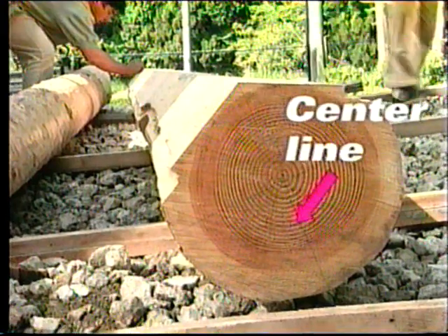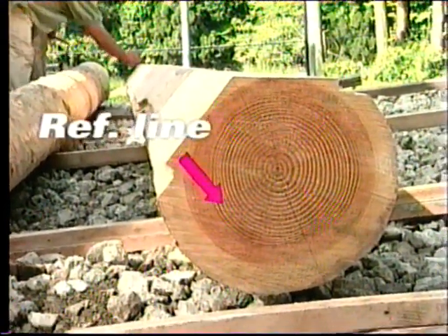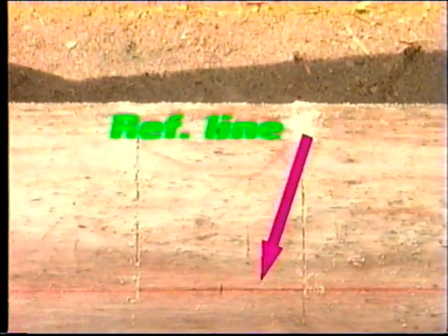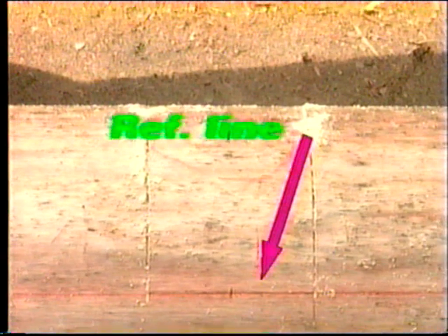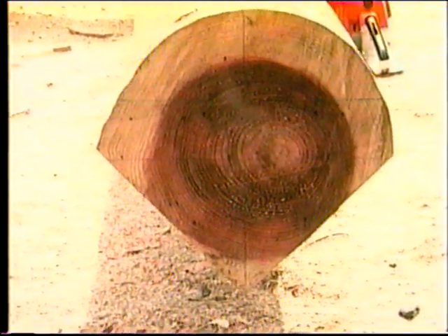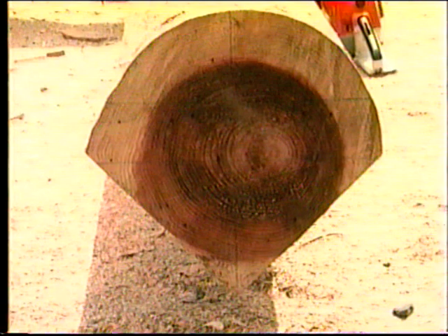Place lines and do the slope cuts, then roll the log onto its side so that you can snap lines vertically down the length of the ridge for the reference height line. Turn the ridge log over so that the peak is down, then snap a center line on the bottom of the log. Use the plumb lines on the ends to ensure a vertical position.